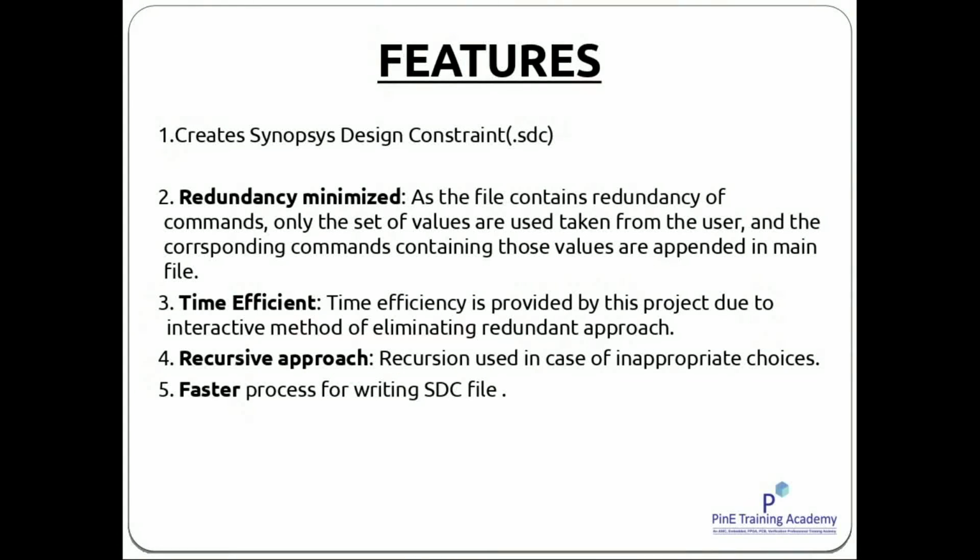It also follows a recursive approach. What we have done is encased each case command in a particular function, which is later called in the default option of that case, which supports the recursive approach. And last but not the least, it is a faster process for writing an SDC file, as it just takes values from the user and all the commands are appended in the file.